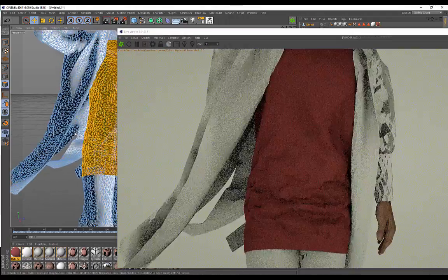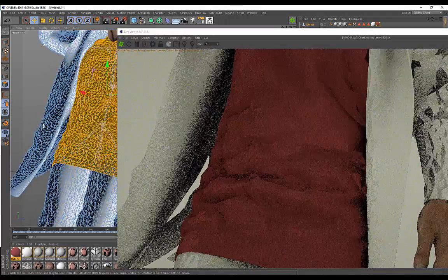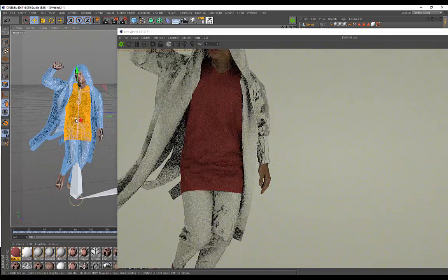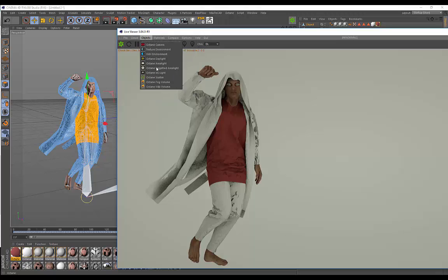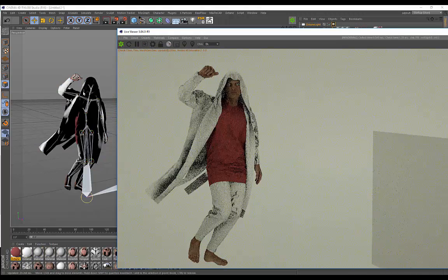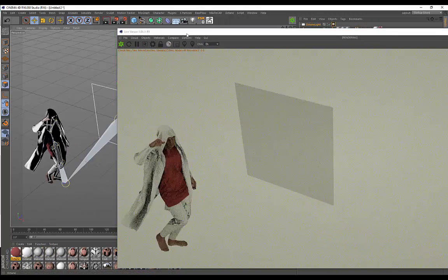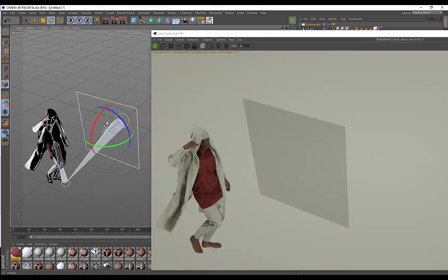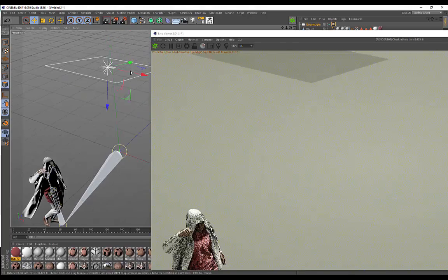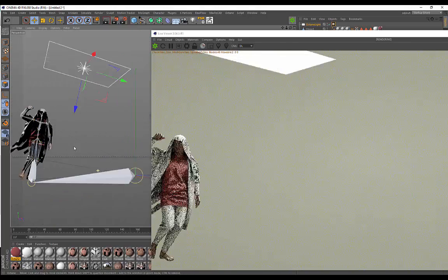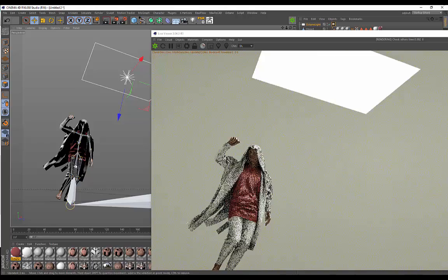Yeah, that looks so extremely low poly because we simulated our animation on 20. So it's really important that you put your simulation for your garment on at least something like 10 or even 5. 5 would be the best,